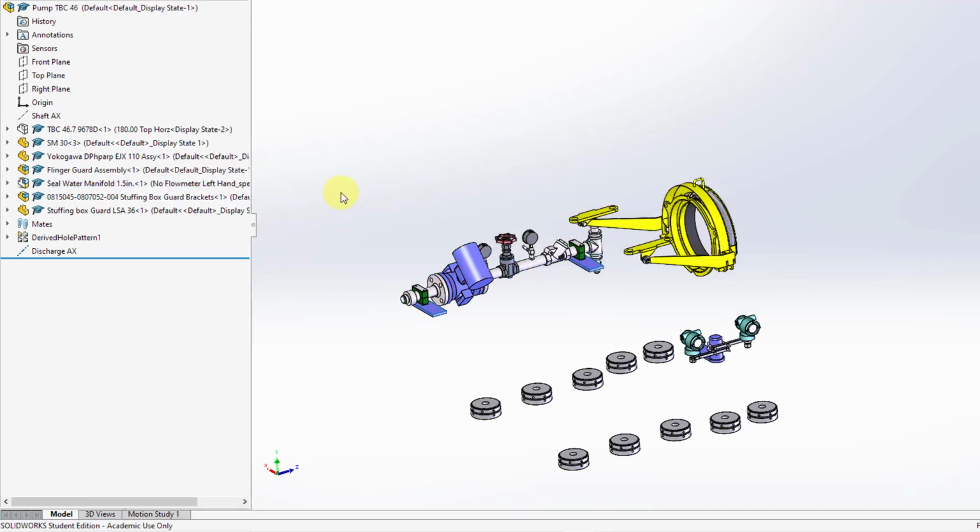When I click on that, the image of the model changed slightly in the graphics area. Let me hover my mouse over the model. You'll notice we're getting some ghosting, and now only a few surfaces are visible and selectable. As I move my mouse over, the ghosted graphics brings back the image of the rest of the subassembly. I've got some other surfaces and entities that I can select, but again, we get those ghosted graphics because essentially you have a nice picture of the subassembly, but only the references that were used for creating various different mates